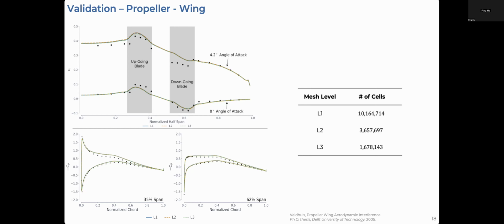The optimization problem that we're going to look at is two-part. Part of this study, we want to understand if coupled propeller wing optimization is worth it, or if you should simply just design a propeller and design a wing and stick them together. So the first optimization problem that we'll look at is independent. So independent is we'll optimize the wing drag alone with respect to wing twist and shape design variables with some additional geometric and problem-specific constraints, such as the lift of the wing must equal 550 newtons, and then we have some volume, thickness, leading edge radius, and curvature constraints that are surrogates for other parts of the simulation, such as structures that we don't include.